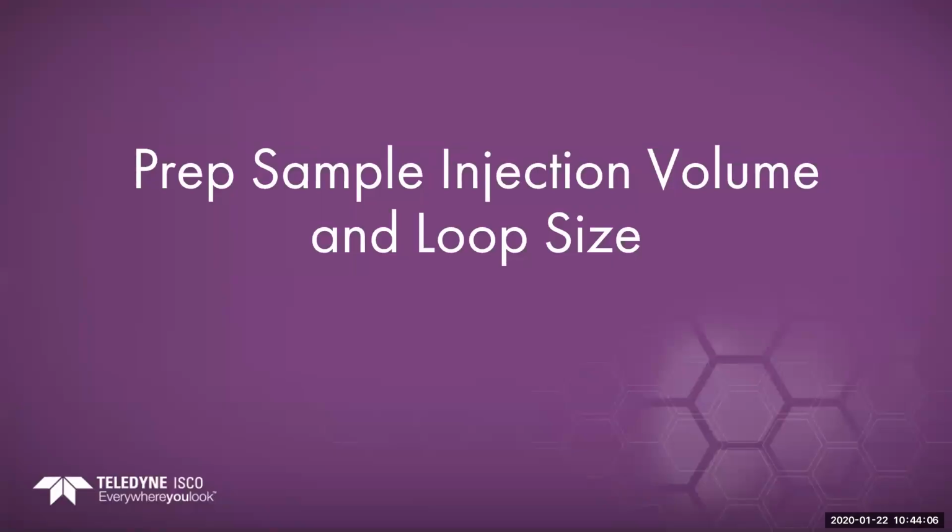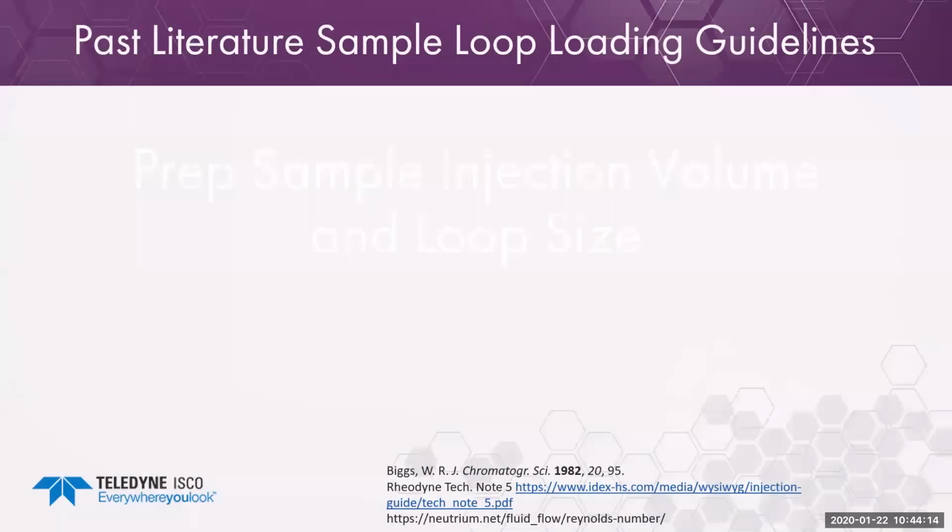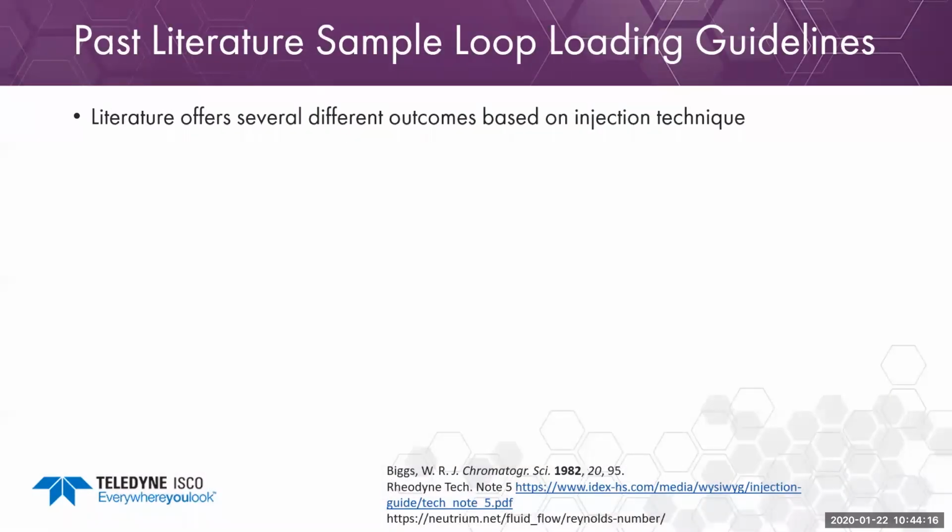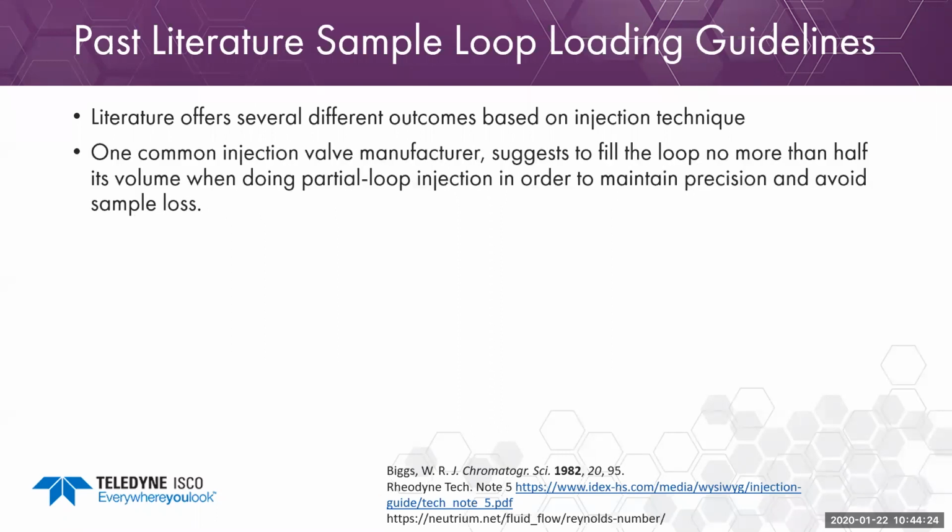And one of the last things we're discussing today is prep sample injection volume and loop size. This is an important consideration: how much sample can I load? Based on some past literature, there are several different outcomes depending on your injection technique. One of the valve manufacturers suggests filling the loop no more than halfway when doing a partial loop injection, which is essentially what you do on prep all the time,